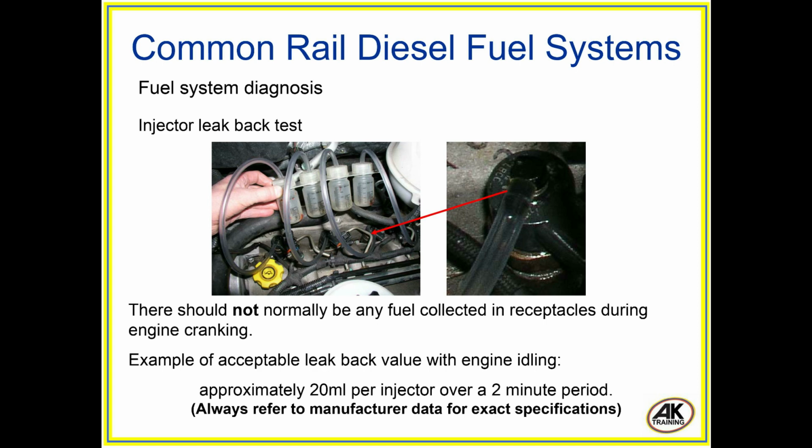Fuel system diagnosis. Injector leak back test. There should not normally be any fuel collected in the receptacles during engine cranking. Example of an acceptable leak back value with the engine idling: approximately 20 ml per injector over a 2-minute period. Always refer to manufacturer data for exact specifications.